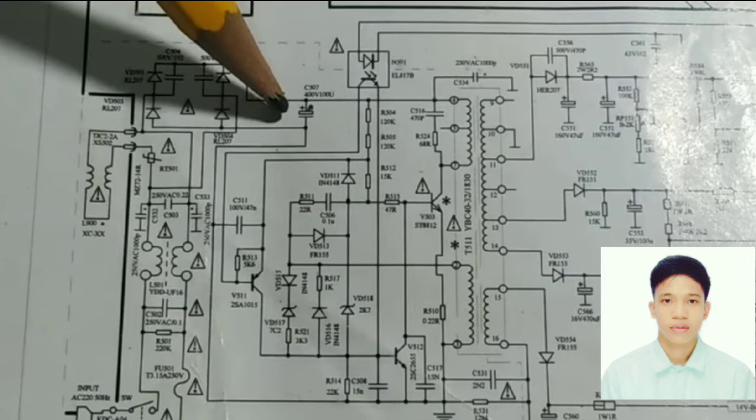After that, it also has a filter capacitor whose main concern is to filter the unnecessary AC signal that enters the diode. And if this capacitor changes its value or opens, there will be a lack of filtration, which means it produces ripple frequency wherein it gives a disturbance, and you will see on the output of the television that it has a hanging bar, or the picture is getting small. In that case, there is an issue in the power supply or in the filter of the primary.